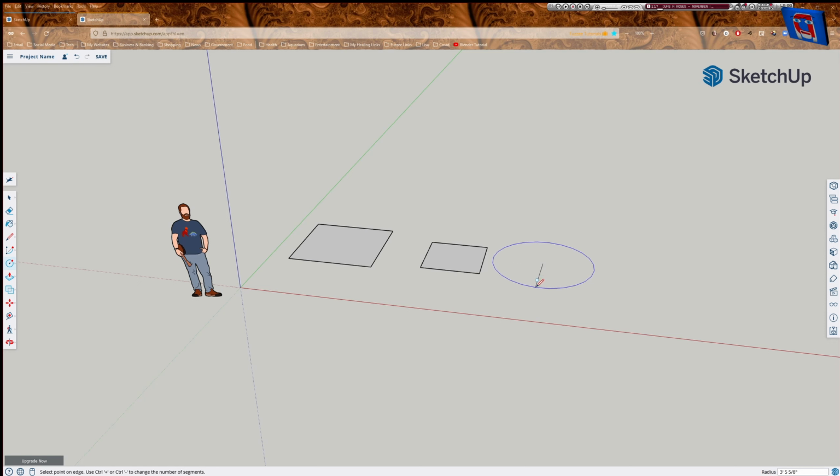So once again, we can draw a circle, and I'm actually breaking the rules because I'm dragging this circle when I shouldn't be. So we're going to get rid of that. So once again, I just click and release, and then I drag it out. And you'll notice when I get to a particular axis so that I'm right on it, it changes color and locks it on. You can also pick the size of your circle and type it in manually, and it's done by radius. So we can type in, let's say we want this to be 24 inches. So I'll just type in 24, hit enter.